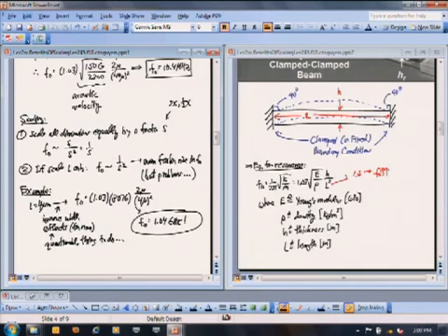Okay? Yes? So a couple things. First is the equation you get for the clamped-clamped beam. Yeah, so I'm not showing you all of those different things. There are multiple modes, and in this case, a flexural mode is a dispersive mode. So it's not multiples. If I were to write it down, I couldn't just put an i here in place of that 1. They're not multiples of one another. Well, I guess they are harmonics, but they're not multiples. Like your fundamental would be 10 megahertz, your second would be 24 megahertz or something like that, right? It changes with the mode.